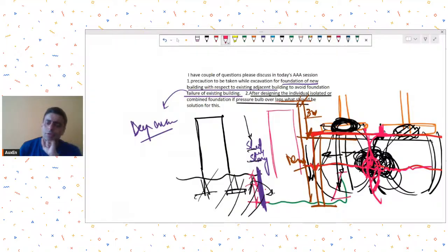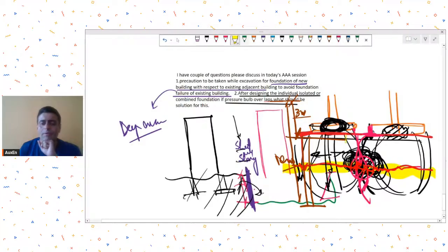So even if there was a merging and addition of the bearing pressures, usually it will be lesser than the increased SBC that you get at deeper strata. So generally, pressure bulb overlapping is not paid a lot of attention. But it should be thought about. Generally, practicing engineers don't give a lot of attention to this aspect, probably because of these two reasons.